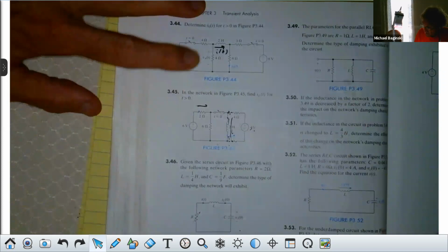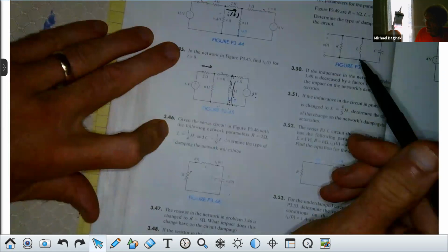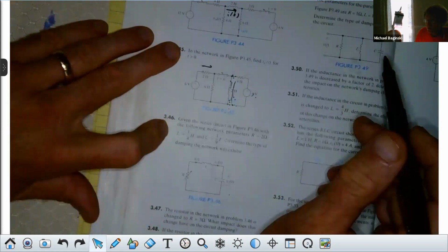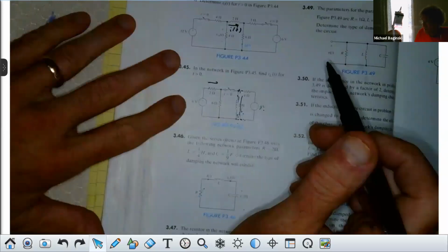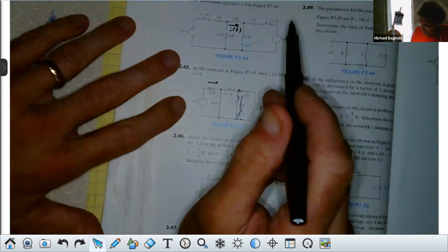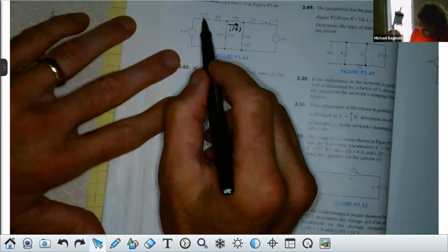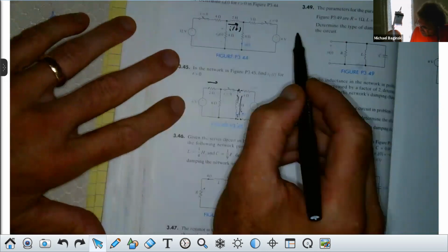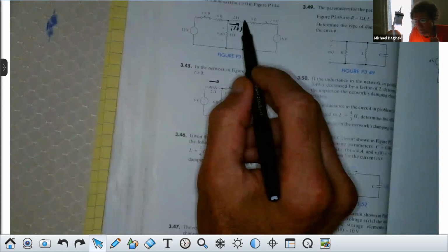Now, having said that, I want you to look at this. This is the kind of problem that I'll get all sorts of complaints about, and some of these are justified because it requires several things to think about. It's not just one or two little things. If I want that current and I have 4 ohms, this switch is closed and 12 volts, and I have 3 ohms and 6 volts, you could put a voltage here and do nodal. You could use mesh analysis,